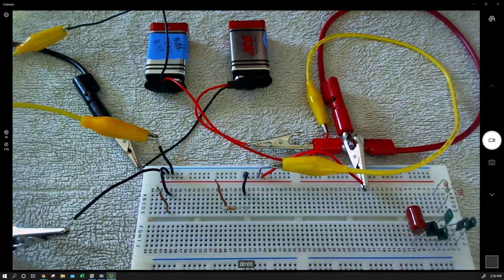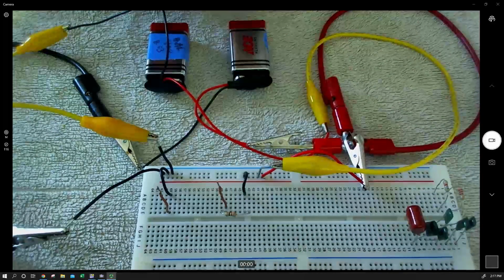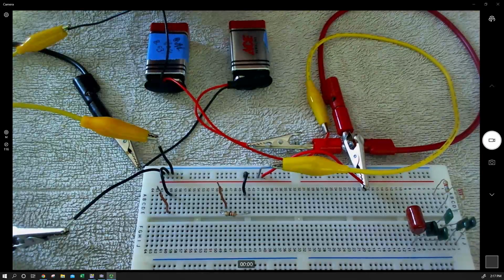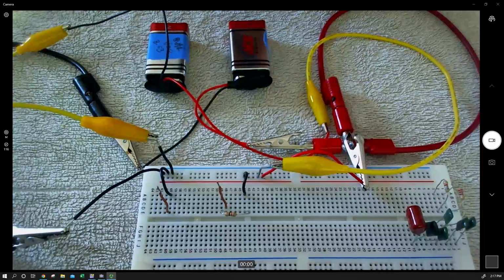So let's go ahead and compare that to what we would expect via Ohm's law for using an open circuit 8.63 volts and our nominal 82 ohms. According to Ohm's law, if our load circuit were the only thing limiting, we should have been able to measure about 105 milliamps. And so even with our dual source, we could only get 95.